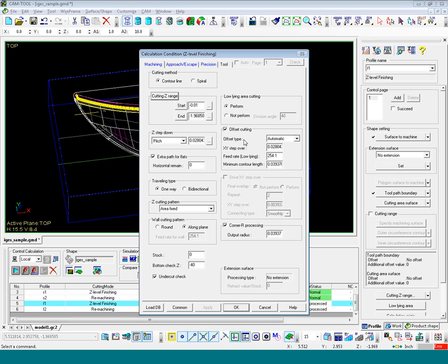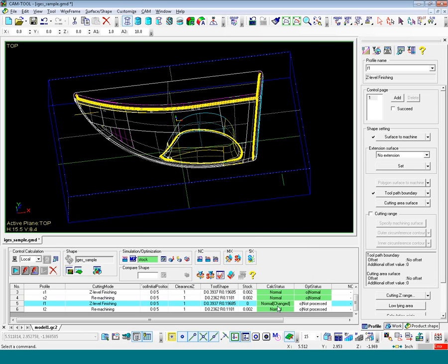So we use something called offset cutting. Offset cutting enters tangent to the surface it's cutting and exits tangent to the surface. So it's sort of like it's dusting on those extra moves to make the scallop consistent between your walls and floor and any low-lying areas. Creates a near mirror finish. So let's say OK to that. Well, that one's ready to go.